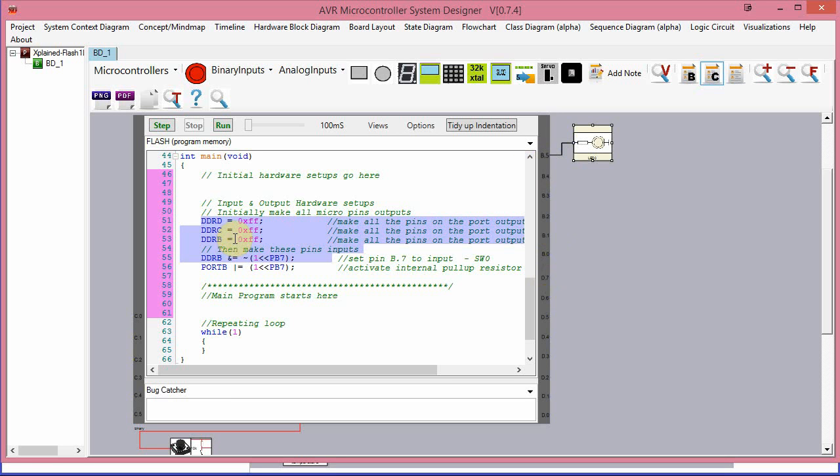What I normally do is I set up all of the pins as outputs to start with, and then I configure the inputs that I want to use. So that, for instance, this is on B.7, and it's a bit of an old habit. These pins, if they're left unconnected and they are set up as inputs, then the potential is to drift in voltage.